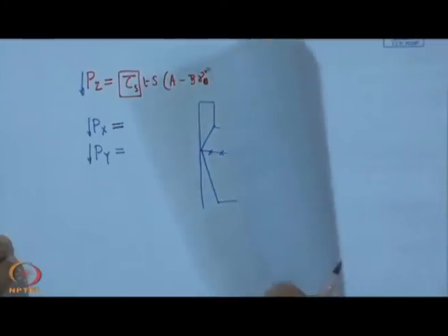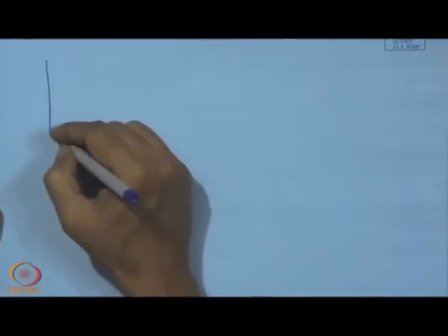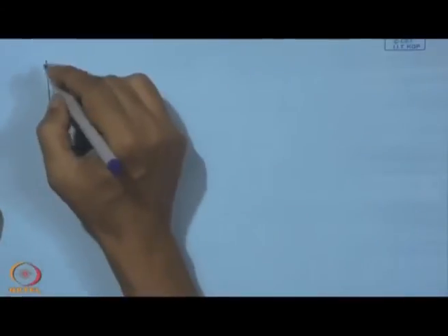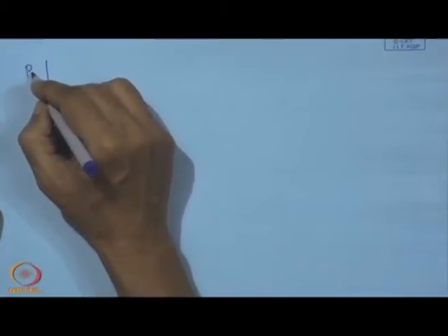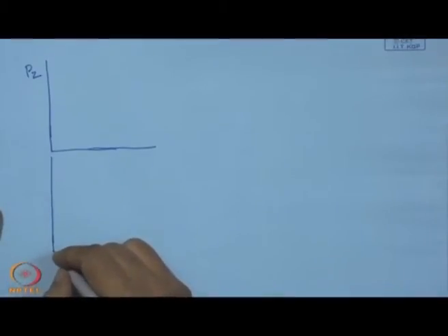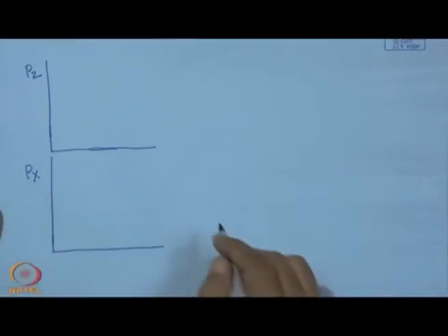Now, one thing we can see here is that we have to use both the tools, that means a carbide tool and an HSS tool. But one thing we must also know, particularly for the force measurement: say this is the force P z and we have a P x force, which is the feed force in the direction of feed.